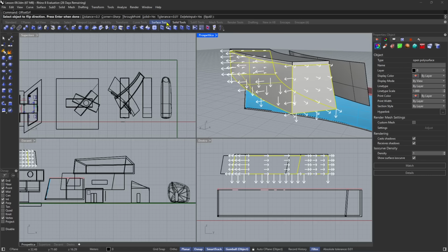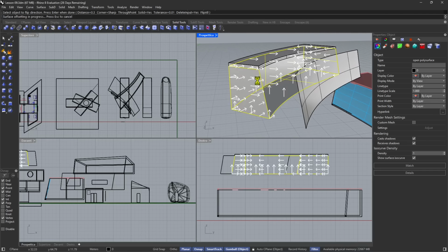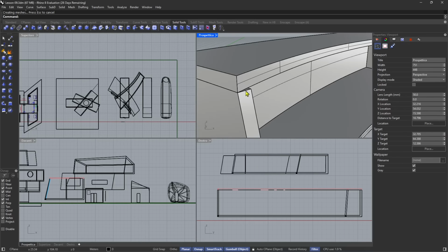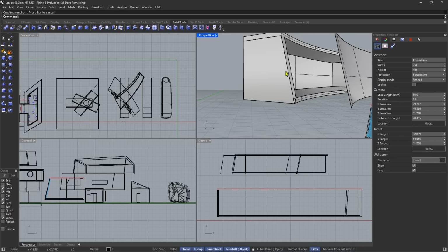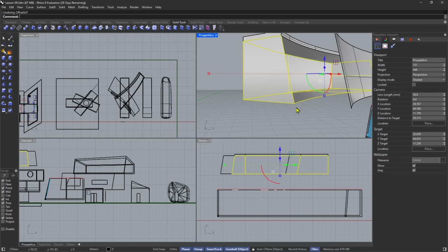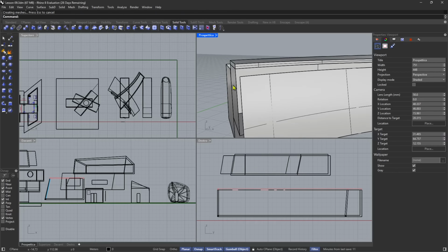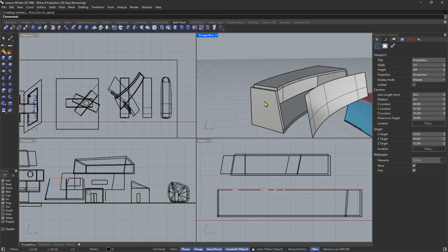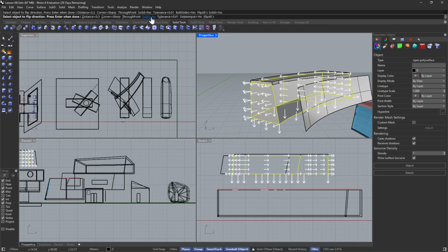So if I again choose a distance of 0.3, I can flip it inside, but this is going to give me other issues. Whether you go inside or outside, you probably need to fix something. You can see here this little issue, but overall it looks fine, and you didn't lose this straight line right here. If we go the other way, outside when offsetting, another important thing when offsetting: choose solid yes. Otherwise, if you don't create a solid, it will create a gap that you will need to fill with some other tools like a sweep or something. So better to go for the solid already.